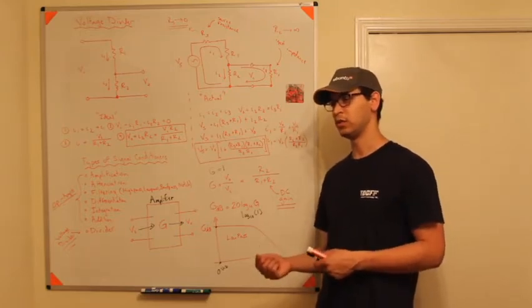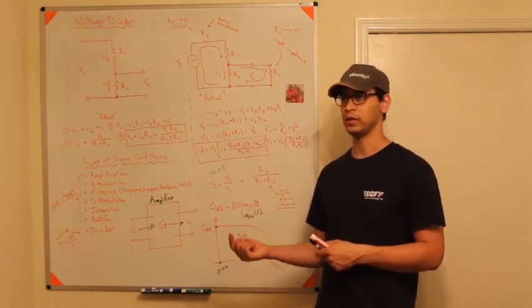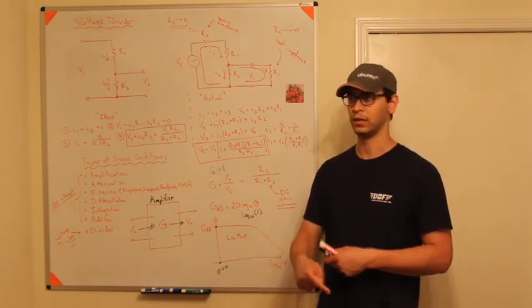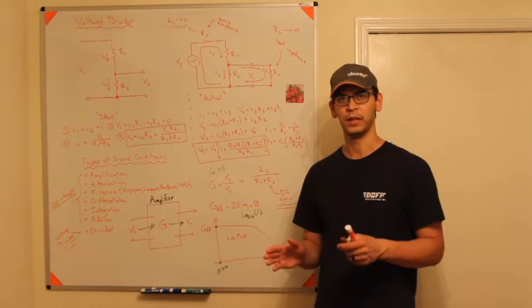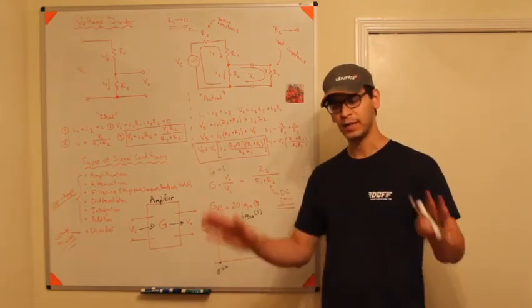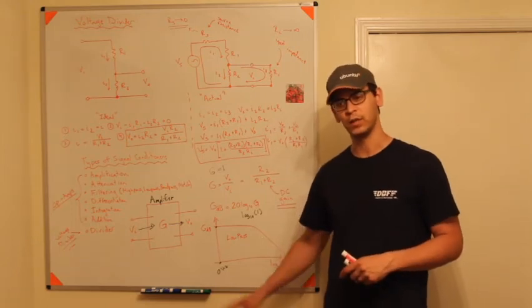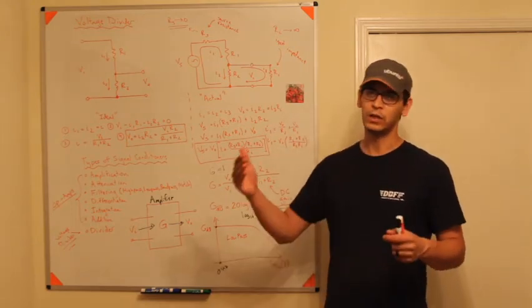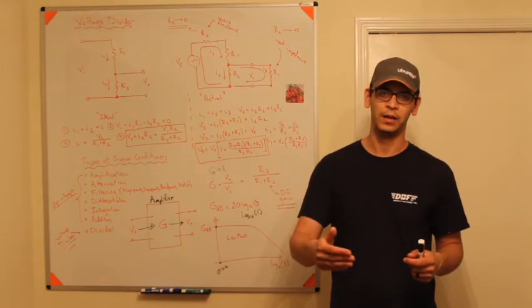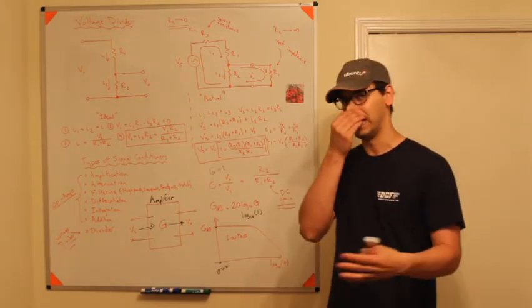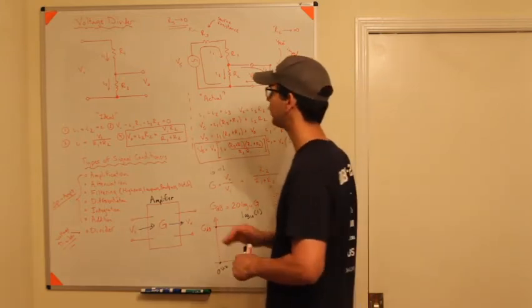Not to mention, you also need to convert it to DC first, so there's that. But I guess that gets into buck converters and things like that. But let's just imagine for the moment that this was a direct current 120 volt. If you plugged this directly into the Arduino, it would fry. So you would need a voltage divider to divide that to 5 or less so that you could actually measure the signal with the analog digital converter on board.